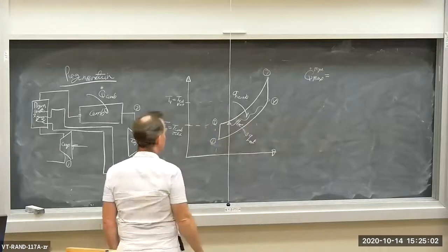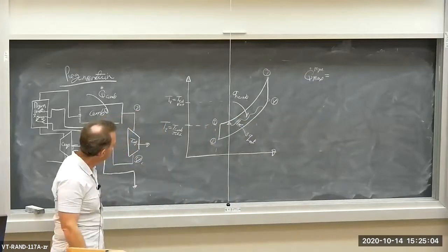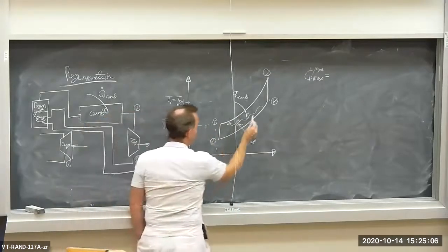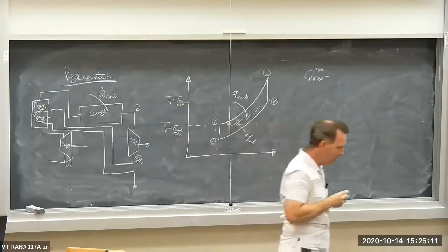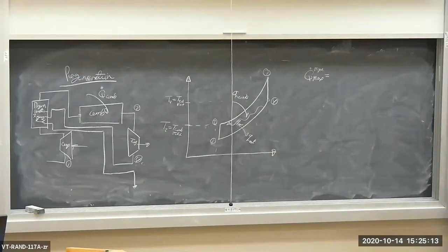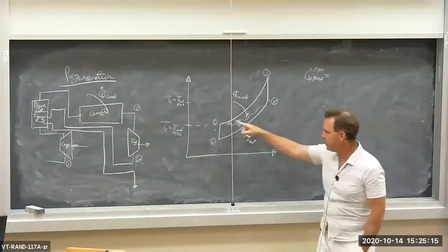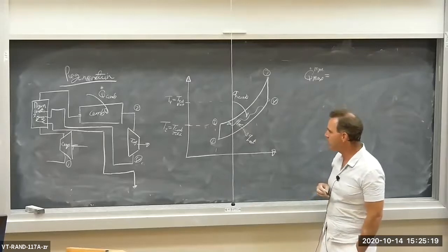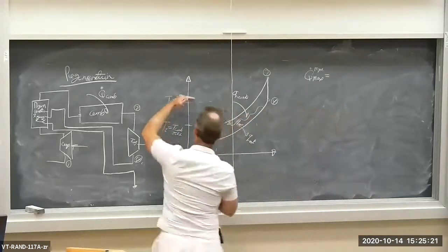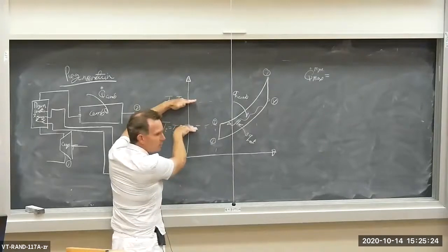Well, clearly the maximum amount of heat that I can pull, in theory, the very maximum amount of heat I can pull from the hot exhaust and shove into the cool intake, is the enthalpy associated with this temperature difference.